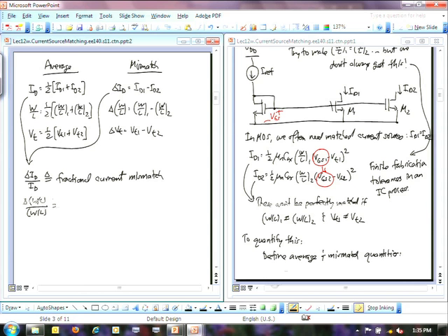Again, I'm looking for things where I'm multiplying two delta terms, because multiplying two delta terms is going to come up with a very small term. And here I see that again. Right here I've got delta W over L times the delta VT. So out that goes. Anything else I can eliminate? Can't eliminate that, no delta terms. One delta term, can't eliminate it. One delta term, cannot eliminate it. So the rest of them stay.